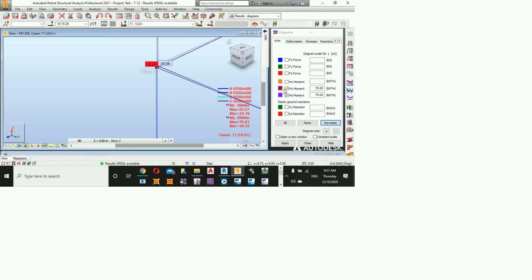Now, do you remember when we said we normally design our foundation in Excel and Brocon and TEDS and whatever? So finding these values are not a big issue, because actually we are going to use the software to design them for me. But I need to get the values of the foundation, because we might be using other software to design. So for the foundation, when you finish from any of the values, you remove the ticks, because if you have a lot of ticks, it's going to be hard for you to see. And then click on apply.